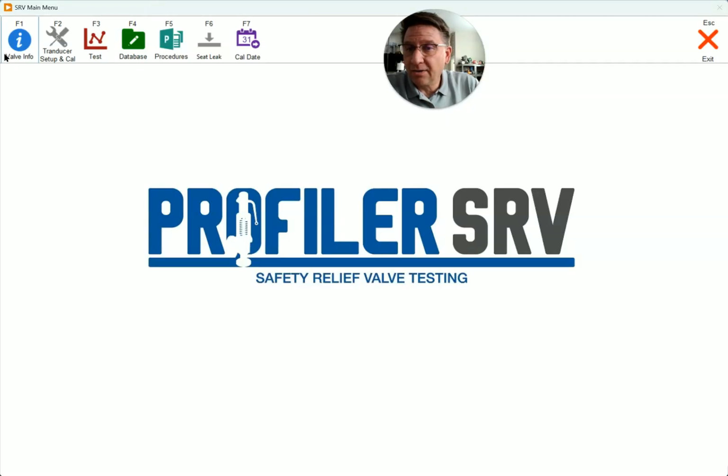Okay, so as we leave this screen, we have now entered the valve information. We have gone in and verified our calibration check sheet, and once we've entered these in, this will be ungrayed out. So we can now go into here and run the test. We're going to run 4 tests. Okay, one, we're going to demonstrate the as found. Then we're going to test the next 3 for the average of the 3.